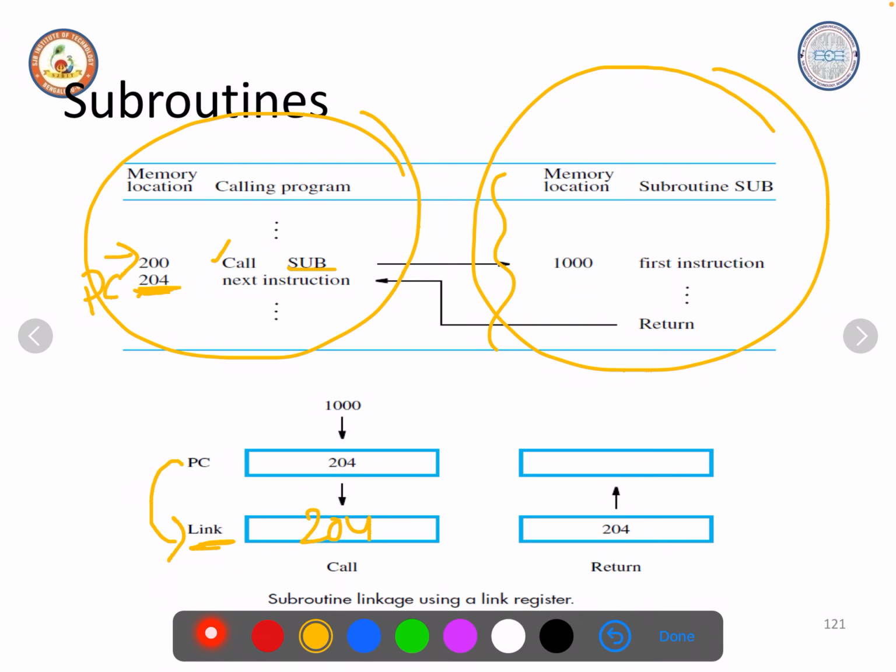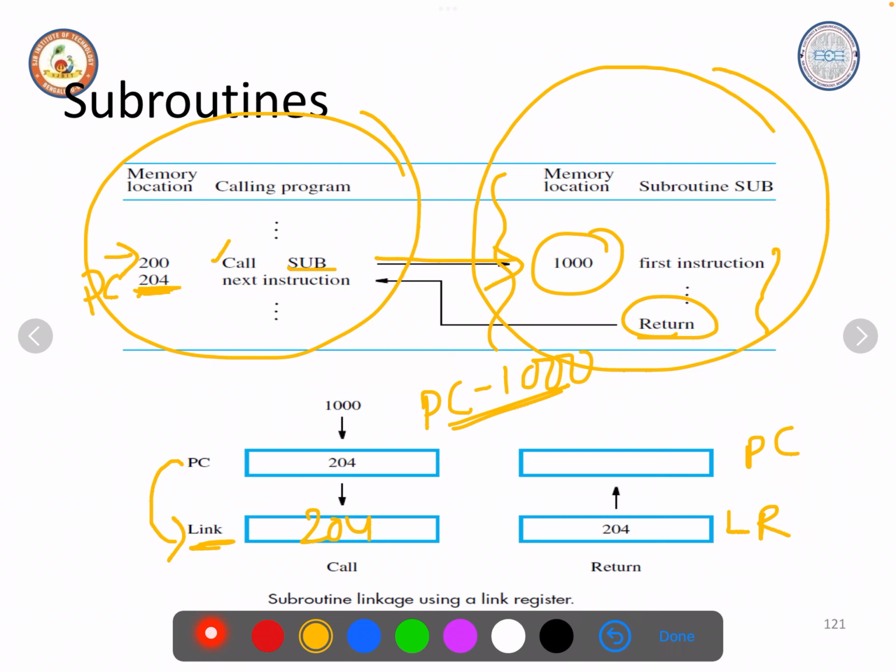Now PC has become free, so PC will be loaded with the address of the subroutine. Subroutine address is 1000. That will be loaded into PC. So PC will be routed to this and it executes the instructions in the subroutine. Upon completing, you will find a return instruction. Return, what will it do? The link register content will be loaded into PC. So PC will now have 204, which is the address in the calling program. It executes the instruction from here.